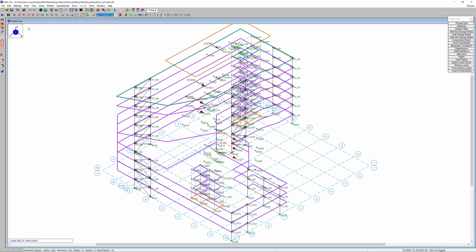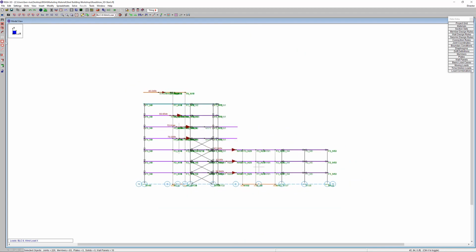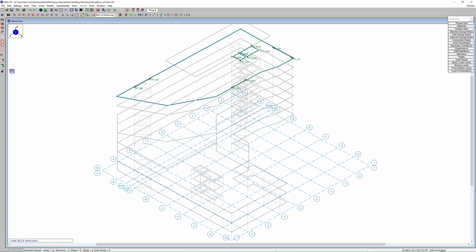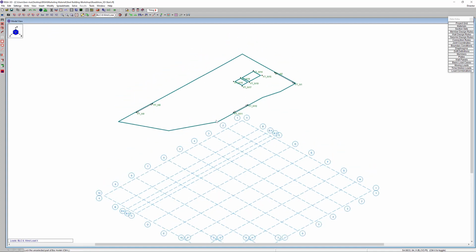And I'm going to go ahead and do the same thing. I'm going to get a side view, and let's just deselect, and I want to select only the semi-rigid level here. So let's just select that semi-rigid level and lock everything again. And so when we do that, I think we should be able to see our semi-rigid loads applied to the structure at that level. And remember, those semi-rigid loads, because we have a mesh, are going to be applied to the edge of it, rather than at a central node in the system, because that load is going to be dragged through all of those connected mesh elements.